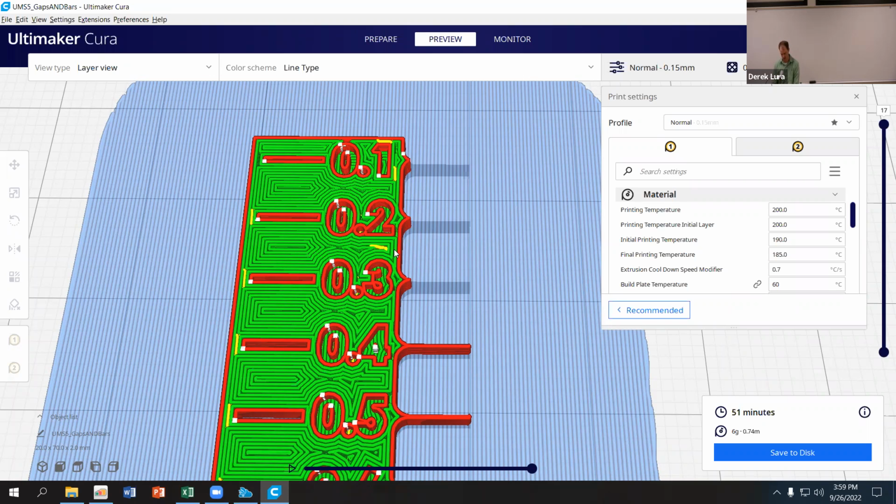And if I were to take a caliper and measure the width of this last tab, you can see that it's not consistent because it actually moved around a little bit. It peeled off the build plate. I don't know if you guys can see the fact that that last little bit is kind of loose and blobby. But it's not going to be exactly the 0.4. It's going to be 0.4 plus or minus something along the length. Same thing for the 0.5, the 0.6. It's going to change as I go down. Then as I get bigger, it might stabilize a little bit. We're always going to have some geometric error in the printer as a result of going through that.